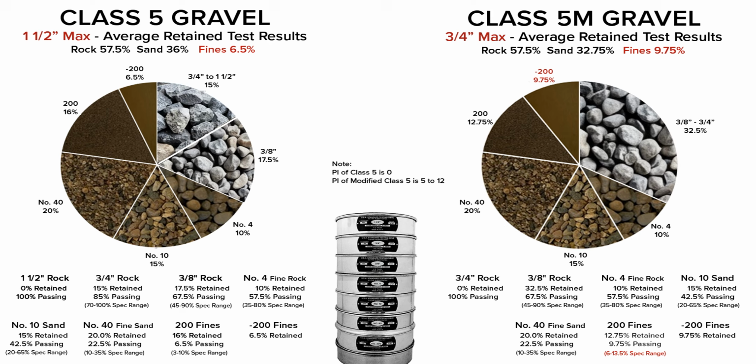As an operator, your takeaway for this section is that surface gravel, Class 1 and 2, is designed to lock and seal, while base gravel, Class 5, is designed to support and drain. Surface gravels use smaller rocks, under 3/4 of an inch, and a higher percentage of fines or clay binder to create a tight, waterproof crust that resists washboarding. In contrast, standard Class 5 base gravel has larger 1.5-inch stones and fewer fines, allowing water to pass through the foundation rather than trapping it.